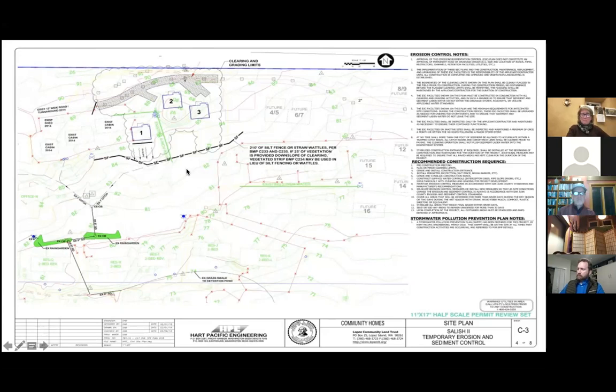Well, this is something I learned in the class, because once you get used to looking at silt fencing, you'll see hardly anyone ever puts it in correctly. And it actually doesn't hold back any silt. Now, I know some people are real good at it, but for the most part, they are not. Somebody tells them what to do and they go out there and stake it in. And when you see heavy rains come, it's just washing right under that fence.